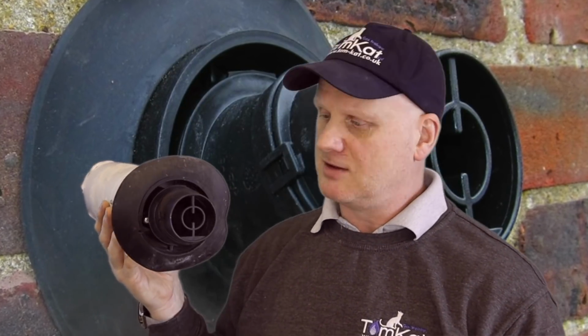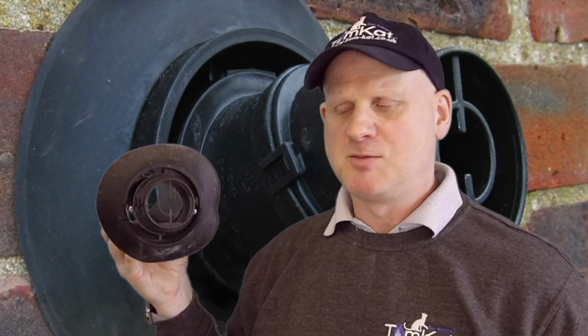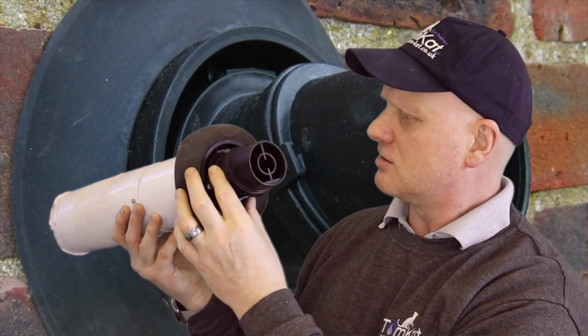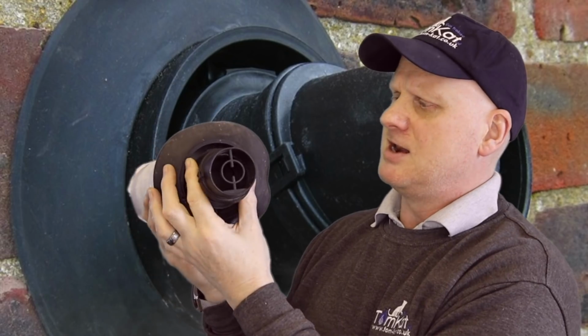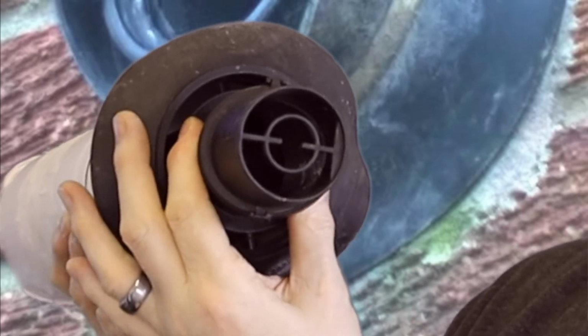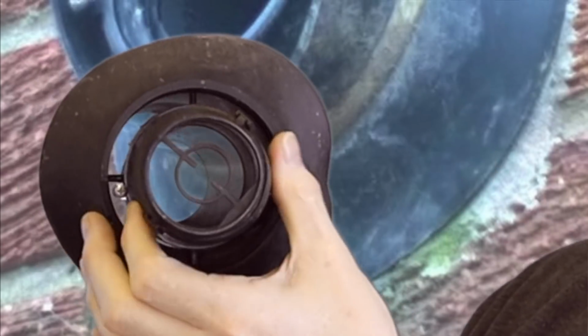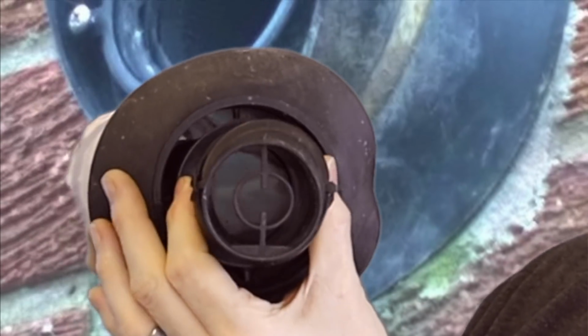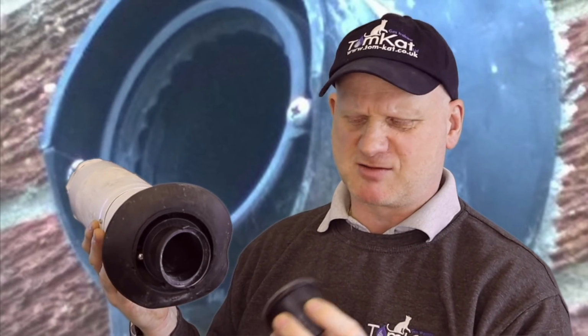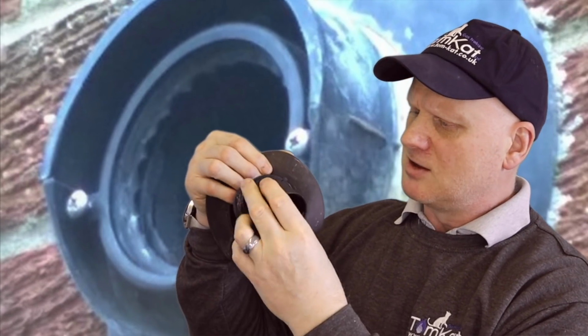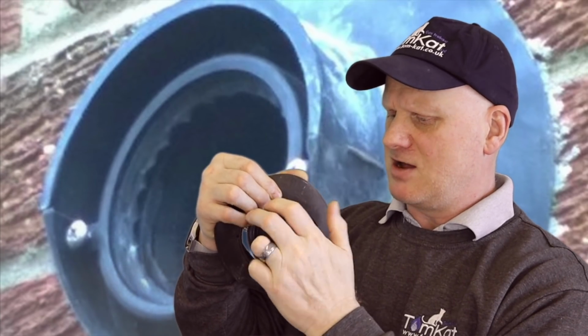And if there's anything good about a Worcester, it's this flue system. So this is the terminal, and basically we've got two screws here, and if we twist it, you can see it spins, but it doesn't spin all the way around, and that'll become apparent in a minute. Those two Phillips screws there secure it and allow us to divert your products of combustion. You can see this splits in two ways, so there's two securing clips. That's where it came off easy because I'd already undone it. So if I clip that back on in that direction,